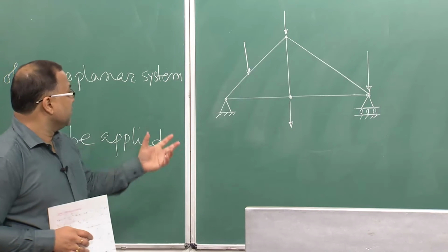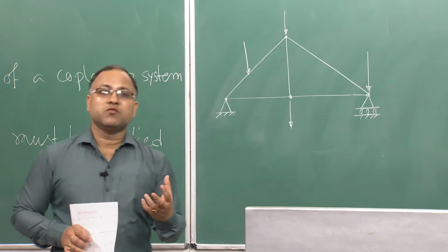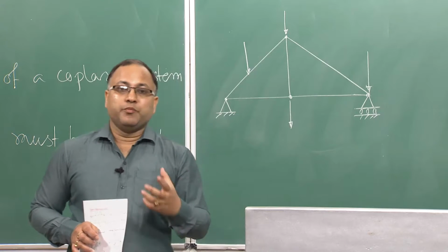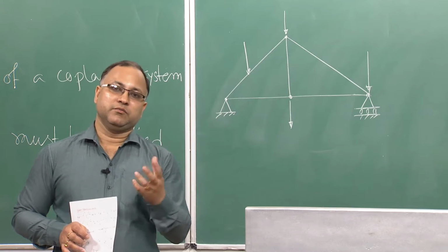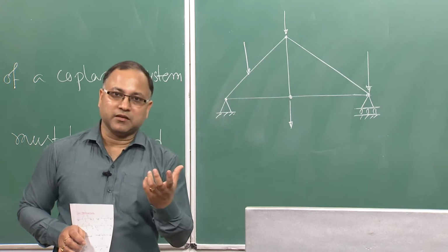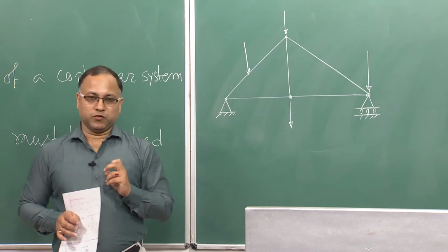Member forces means there are 5 members in the truss, and how much force they are carrying. Based on those forces, you can design the member, that is the idea. So, you need to analyze the truss to get the member forces.